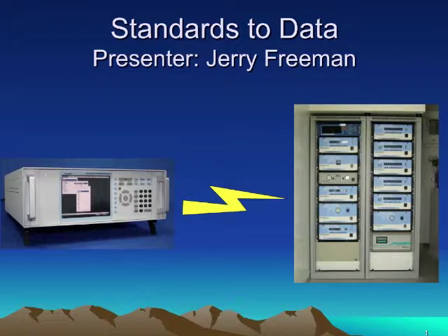When you guys calibrate, do you calibrate to the back of the instrument or through the probe? So for an ozone-only site, we go through the back of the instrument. And then if the site's running a multi-calibrator, we typically would go through the manifold.